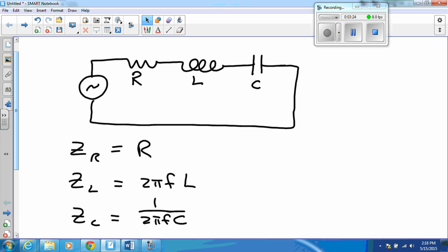I have a question. If you have a circuit with just a capacitor in it, you still have a little bit of resistance because of the wire, 10 to the minus 5th ohms, something like that. So you're going to have a really, really small time constant that's basically negligible. By the time your thumb comes away from the power supply switch, it's already charged. So when he said it was almost instantaneous, it's like a really, really steep slope? Yeah, that's exactly it.